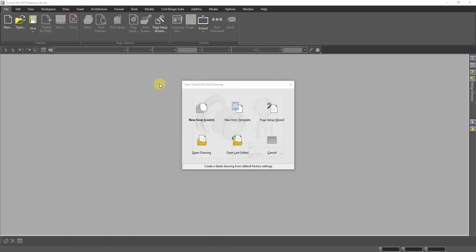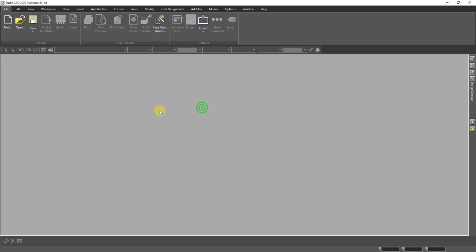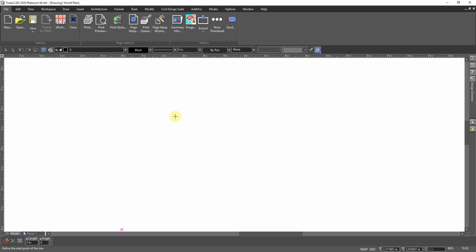Okay, in this video we should try to just change the system. This is how I assume most of you opened TurboCAD the first time. And if I then go New from scratch, we see it is in inch. I don't work in inch, I work in the metric system. So the first thing is to go and change that.